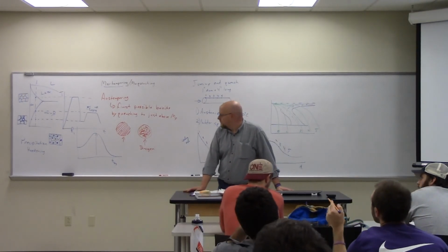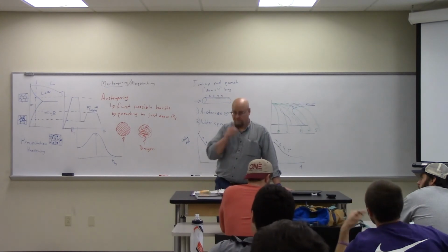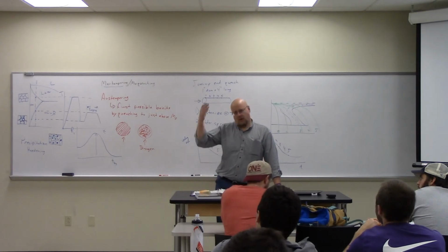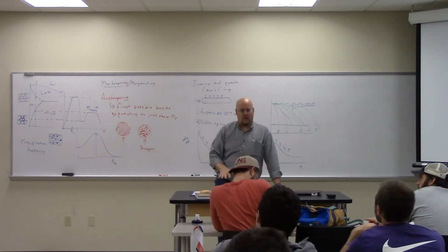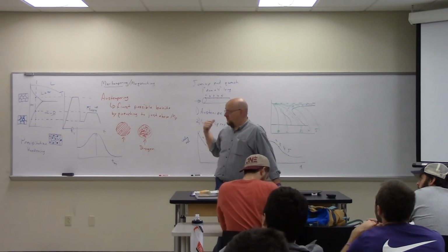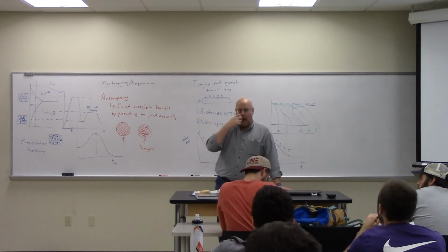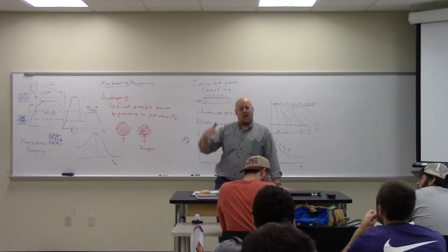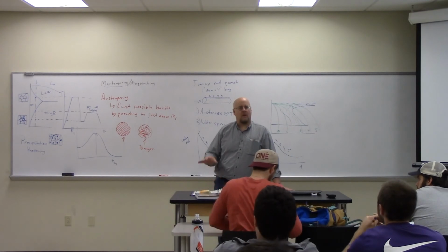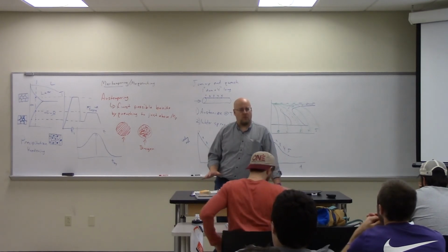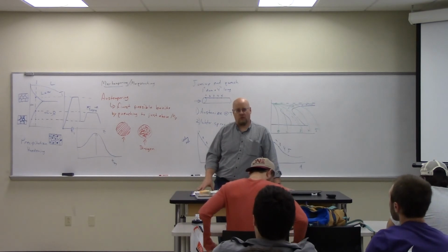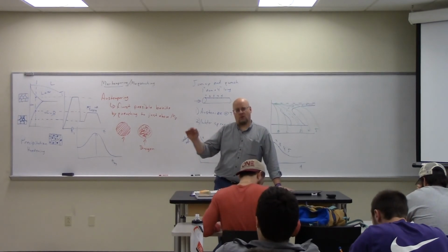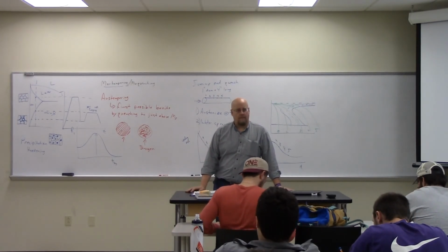So that really fast drop, we're quenching it so that it's just all alpha? We're quenching it so that it is room temperature, all alpha at room temperature. Or we're quenching it down there so that we get below, it's kind of the same thing, there's going to be a similar kind of a knee, in that there's a diffusion and nucleation driving force for the formation of beta. And if we get down below that, then we can prevent any beta from forming because there's just not enough thermal energy to cause diffusion. Or we can minimize the amount of beta that forms at the grain boundaries. And then bring it up gradually so we have more control over where the beta forms.